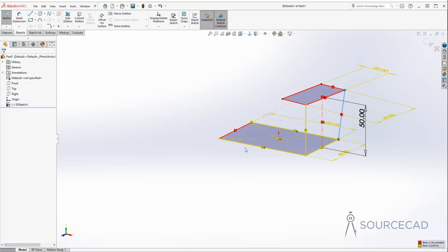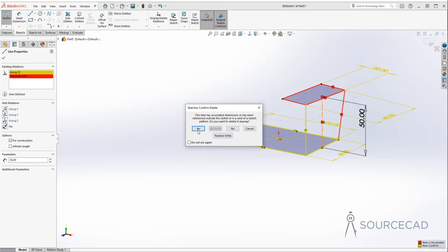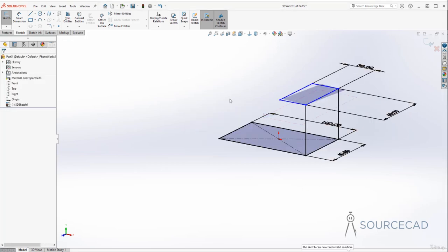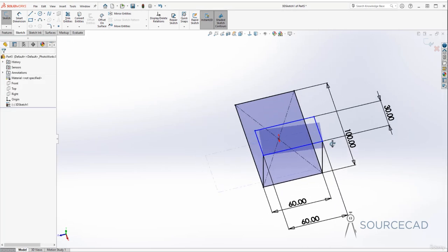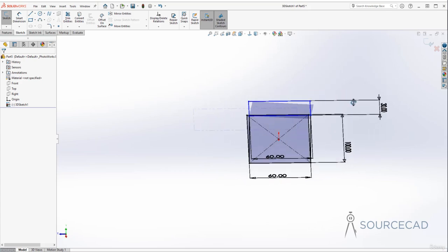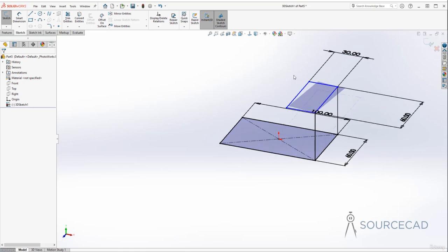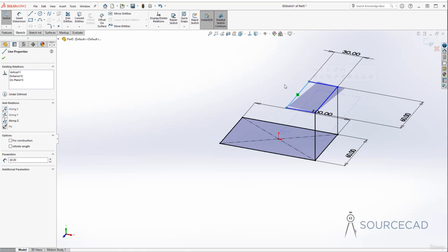I'm just going to click OK, and I'll delete this construction geometry, and yes, and there we are. Now it is completely defined. So we just don't need 3 of these lines to define it, and that's why it was over constrained. So here we are. Now once again, you can see that this line is blue, and that indicates it's not fully constrained because we can still constrain these 2 lines along Y and X axis.